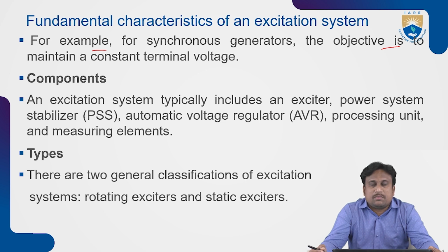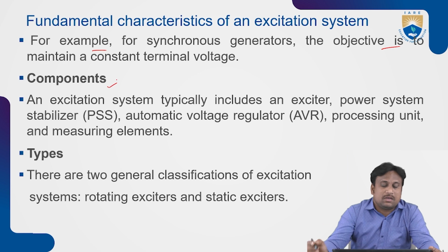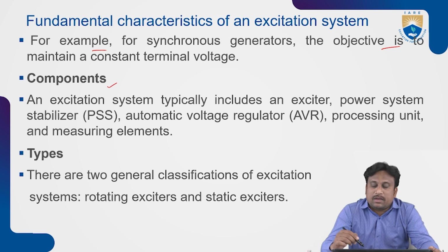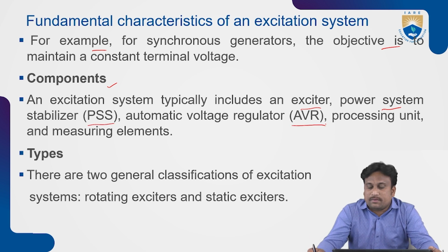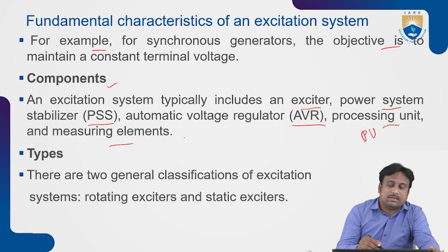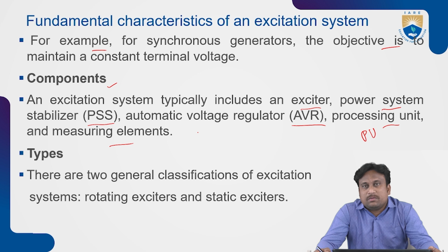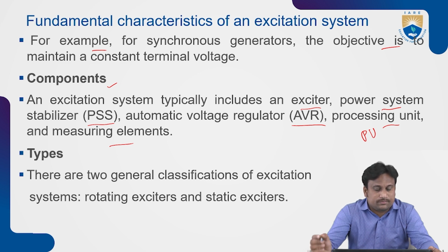The components associated with this typically include an exciter, power system stabilizer PSS, automatic voltage regulator AVR, processing unit, and measuring elements, which measure voltage, current, power and frequency.